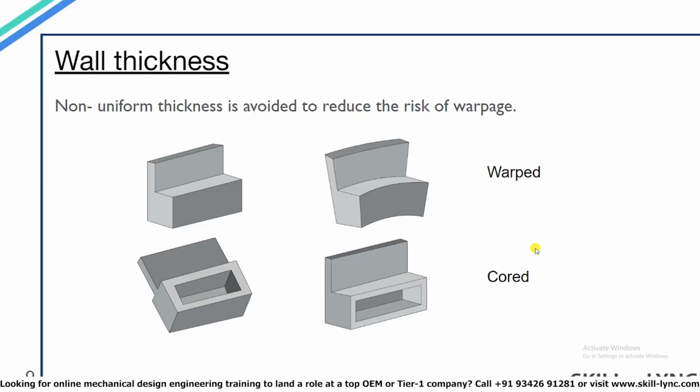Usually the thickness values used for plastic components vary from 0.6 mm to 5 mm. If we try to make parts lower than 0.6 mm thickness, then there won't be a proper filling of material in the mold. The material itself will solidify before reaching the ends. This defect also has a name. It is called the short, which will be covered in the defect section. For thickness values higher than 5 mm, gas-assisted injection molding is used.